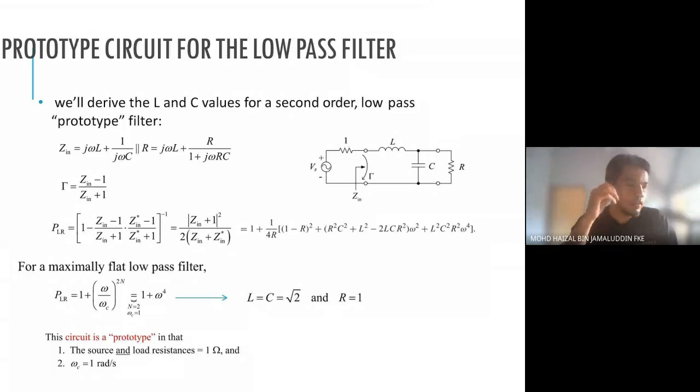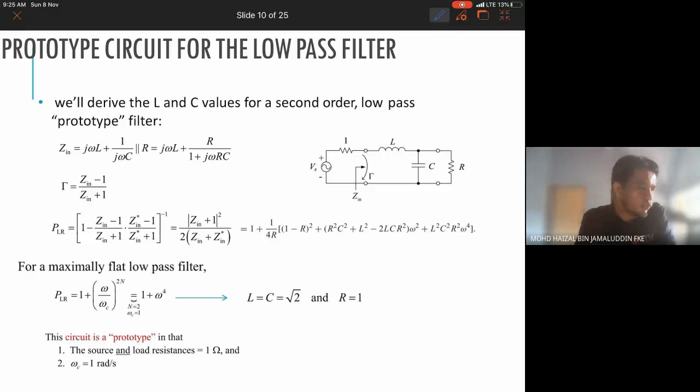So here in this case, for the basic maximally flat filter, we look at the first case. I believe all of you have seen the derivation or, for example, the basic circuit of a prototype, which includes an inductor and a parallel capacitor. And here we have the load, and here we have the source resistor or impedance, which normally we normalize to 1.